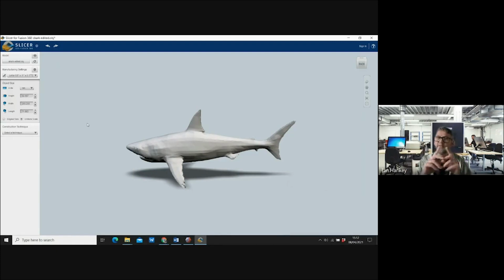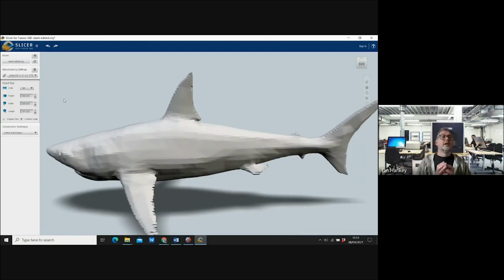What I want to do is make that 400. If I hover over that 203 and then left click and drag, make all that live, and then just type in 400. Once I've done that, I'm going to hover around into the gray area here and just left click. And now the whole thing has become 400 from tip to nose, millimeters across, and everything has actually scaled uniformly.